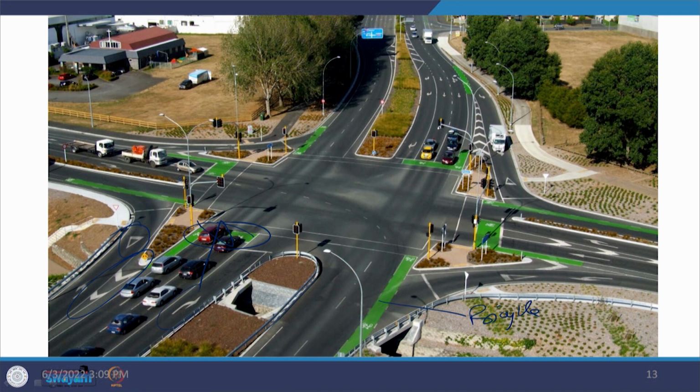So, the arrows which are specifying the directions in which the traffic can move, and the various types of channelizations which are there, which segregate, say, the through traffic and the turning traffic. So, all of those things have been done perfectly, and again in this type you have a flaring also on this side, because there is a lot of traffic which probably is going in the through direction or the straight direction, as well as there is a right turning traffic and the left turning traffic. So, they have been done perfectly.